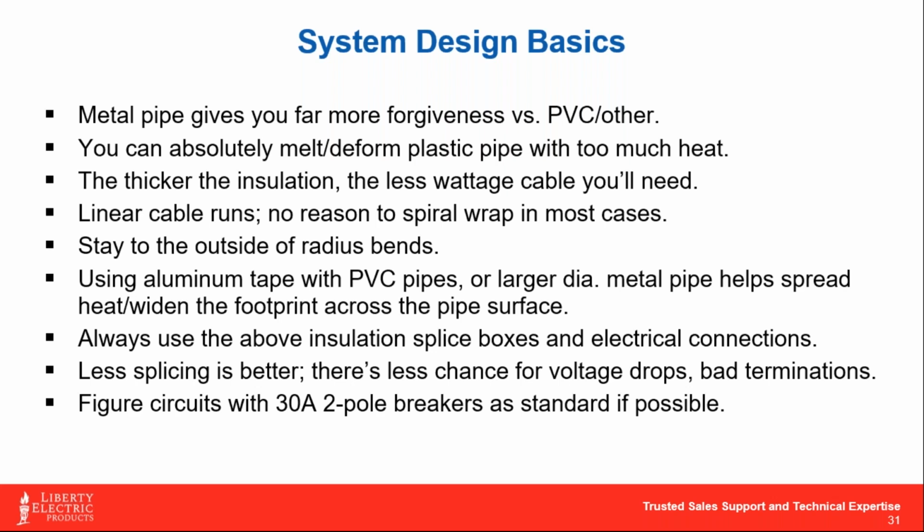So if I'm using an 8 watt a foot cable for a 5.5 watt a foot application, yeah, I've got no problem there, because the metal will take it. PVC, you've got to kind of watch how much heat you're putting on it. The thicker the insulation, the less wattage cable you'll need.